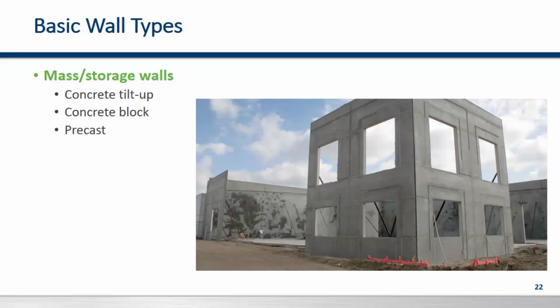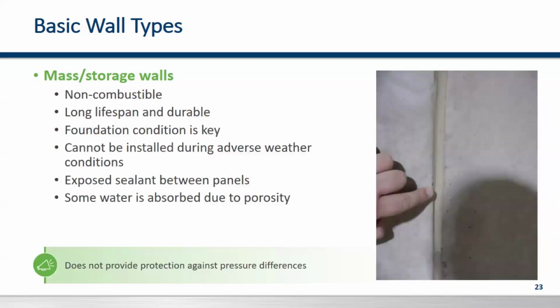However, the creation of the walls, the foundations have to be very strong and solid because of how heavy the panels are. Also, weather considerations when these buildings are being installed, as well as sealants with the use of them. So while they're very durable and long lasting, there's some maintenance that has to be done with them. The construction is important. We have exposed sealants there that will need to be maintained. And then the overall aesthetics.